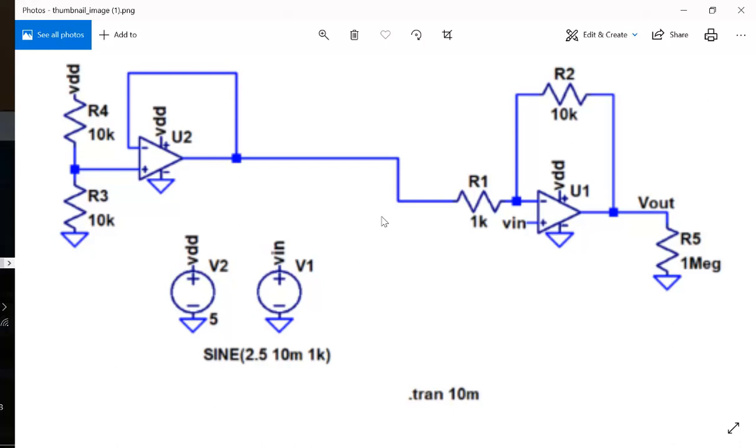Okay, and I have to lift the other side as well. You are not grounding this guy. But how do you lift it without affecting the resistance? Because if you put a resistor here, it's going to divide this resistance. It's going to fight a lot of things. So I have to put a buffer in here. This is called a voltage follower. It's a unity gain amplifier. The gain is one, but you are isolating your voltage divider network from the gain resistors here. You have to do it in order to make it work. But luckily, the lab doesn't ask you to do that.